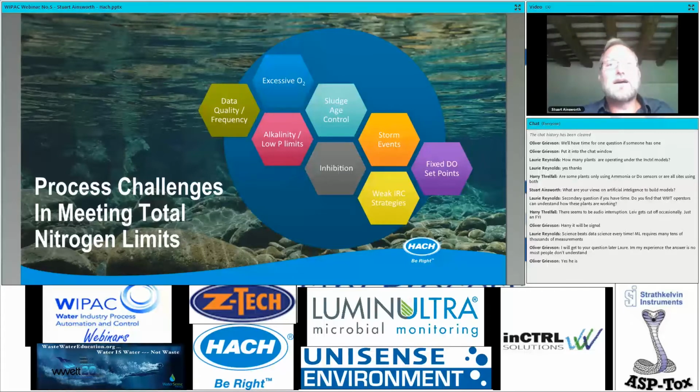And Leiv touched on this before, sludge age control. It's incredible that sludge age control isn't employed more in the industry. Relying on operational staff to calculate the sludge age and to make adjustments and to do that in real time seems a big ask, really, for me.